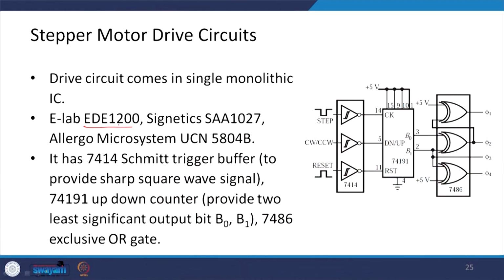There is a drive circuit for these stepper motors, and this drive circuit comes in a single monolithic IC. There are various brands of these drive circuits. For example, E-Lab has ED 1200, Signetics has SAA 1027, and Allegro Microsystems has UCN 5804B.